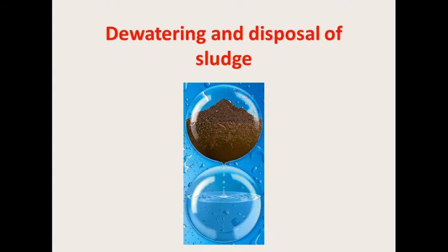That is the suitable treatment, dissolved air flotation thickening, which is suitable for the treatment of waste activated sludge. Here the air bubbles get attached to the solids and cause the solids to separate from the water in the upward direction. The upward moving particles form the sludge blanket on the surface of the flotation thickener. So this is dissolved air flotation thickening.